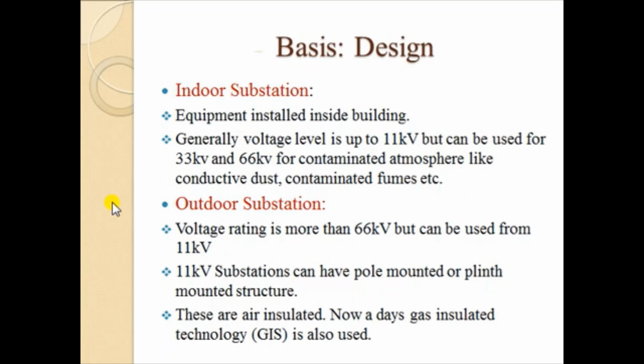So 11 kV substations can have again a pole mounted or a plinth mounted structure. You can have a 2-pole structure, you can have a 4-pole structure. So my appeal is, whenever you are walking on the road, you can definitely observe these kinds of substations with your naked eyes. Now, these are typically air insulated substations whenever you are having a pole mounted or a plinth mounted one. But nowadays, in a city like Mumbai, where you cannot afford occupying space, space is a constraint. The new technology is being used, which is called a gas insulated substation or a gas insulated switchgear, where